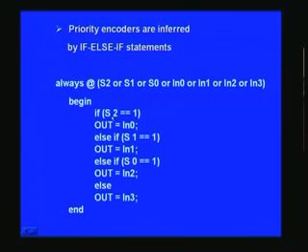For example, if S2 is asserted, then what you need at the output of the circuit, that is here, is in0. If this is not satisfied, only then will it go to this. So not until then. So here it implies that S2 is 0. If it had come anywhere here, it implies that S2 is 0. If it is 1, it would have processed this and got out of this loop as such. And otherwise, if S1 is 1, you assign in1 here, and so is the case for in2. Here what I want to point out, as you are already familiar with this, is how the synthesis tool views this, and how many mux it places. That is the pointer that we would like to show you.